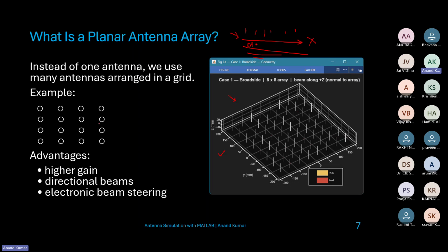In MATLAB you can do a planar array by using the rectangular array function. But if you want a more creative geometry, for example, if you want a certain number of dipoles in one plane and then some others at a different height, then you have to use a conformal array. But if you want to do a planar array, there is a function which just takes in the element and the spacing between them and the phase between them, and then that will just automatically create all this, and then you can study the effects.